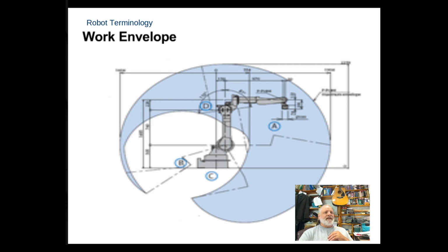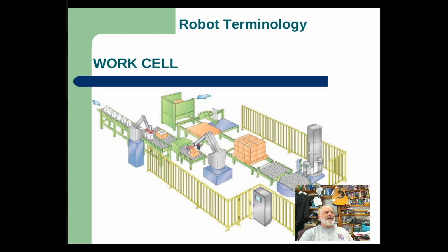But for an articulated robot, the blue area on this slide shows the movement or the adjustment for this articulated robot, or where this robot can get the faceplate to. So anywhere that's white is areas where it can't get to. So you see with an articulated robot, it has a very odd shaped environment there.